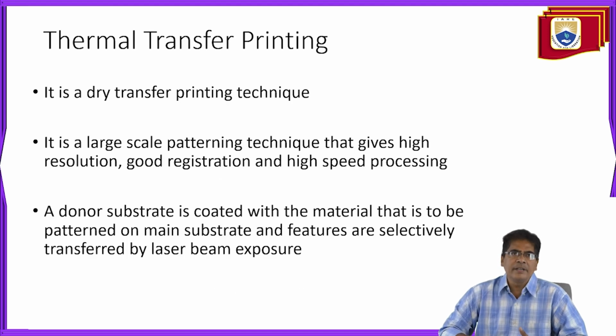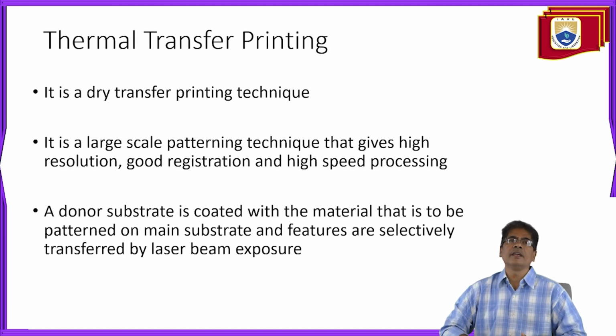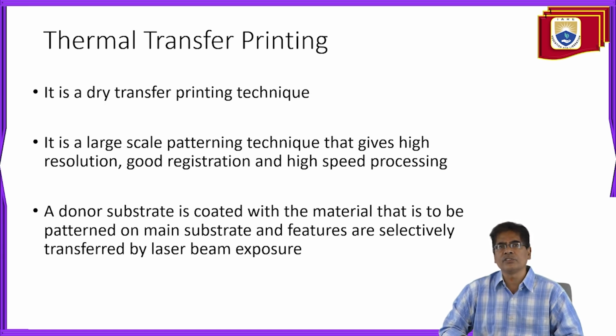So thermal transfer printing is a dry transfer printing technique. It is a large scale patterning technique that gives us high resolution, good registration, and high speed processing. A donor substrate is coated with the material that is to be patterned on the main substrate, and features are selectively transferred by laser beam exposure, right?